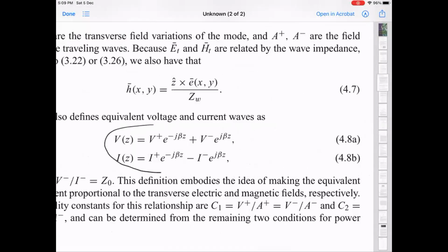These two equations are very handy when you're trying to connect lumped element or circuit elements, whose terminal properties are known, with transmission lines, and figure out how you would actually write down a circuit equation or a dynamical equation to look at what happens.